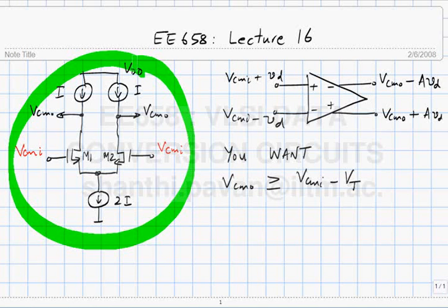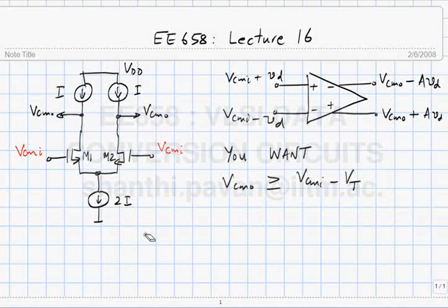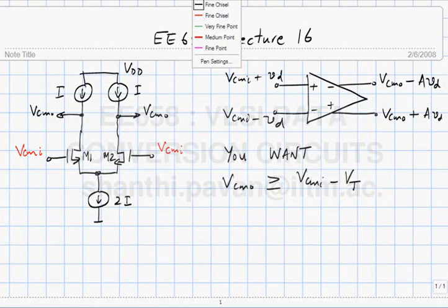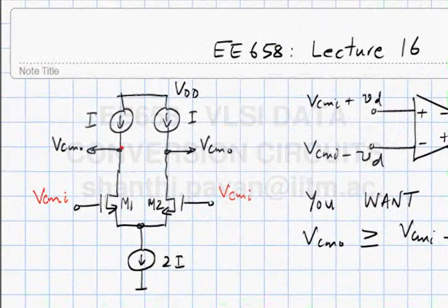The first obvious thing is symmetry. So you can at least simplify analysis, since whatever happens to the left node also happens to the right node. So it is just sufficient. One thing I could do to reduce transistor count and therefore ease up my life is to short the two, as far as analysis of common mode inputs is concerned. Now, can you comment on what this voltage will be?